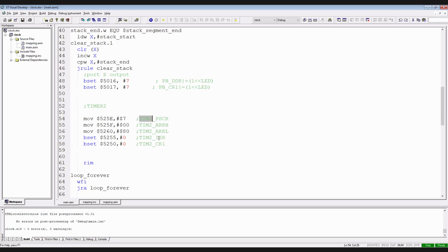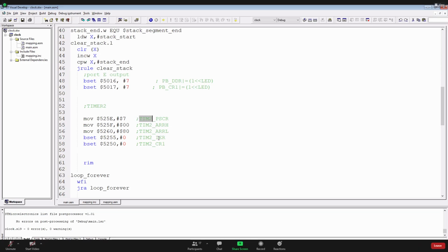Then enable the interrupts on the timer update, so we get an interrupt when the counter is updated, reset to 0 after the time set above. Set the CEN bit in the timer control register first to enable the timer.